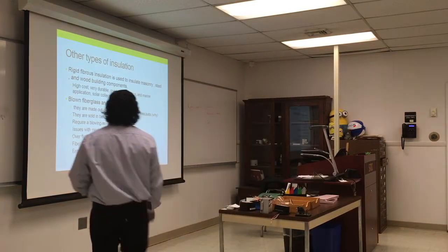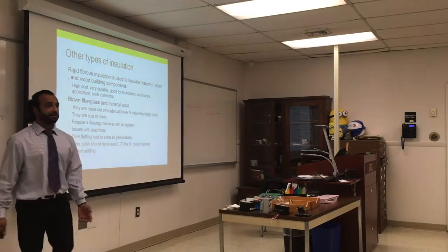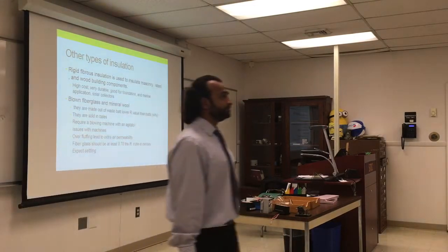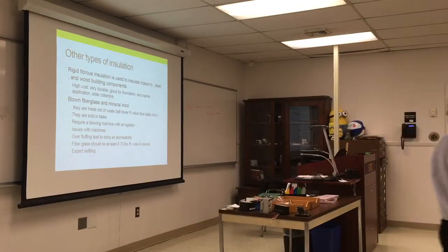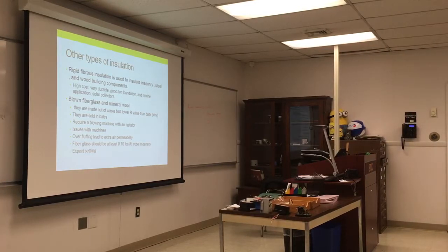Less. So always expect settling. What does that mean? It's blown in, it's fluffed. Eventually it will go down and settle. And when it settles, density has changed. When density changes, your R value changes.